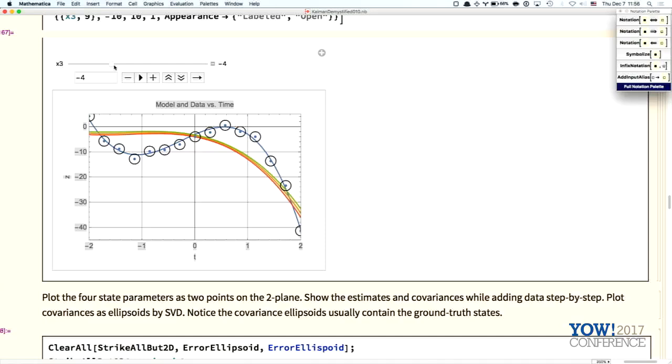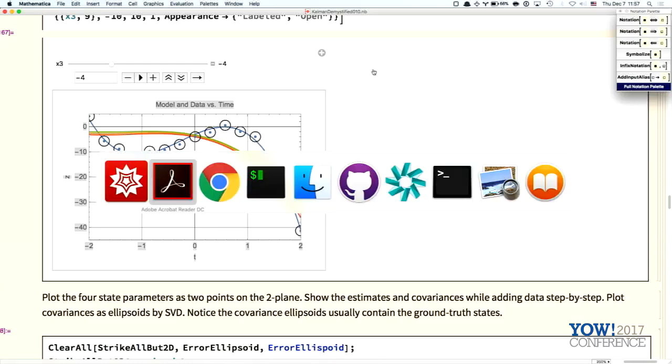If you pretend you know where the satellites are, so in the satellite tracking world, what we do is we have geodetic markers on the ground, and then we have this giant 60-meter telescope that's tied to this geodetic marker, and that tells us where all the spacecraft are. We turn the problem around and we say, well, that geodetic marker in Hawaii is moving with respect to the geodetic marker in Massachusetts. So I add some covariance. How much? Just enough. And by God, you can see a tectonic drift on an oscilloscope, 3 centimeters a year. Hawaii is moving away from Massachusetts at the rate of 3 centimeters a year.